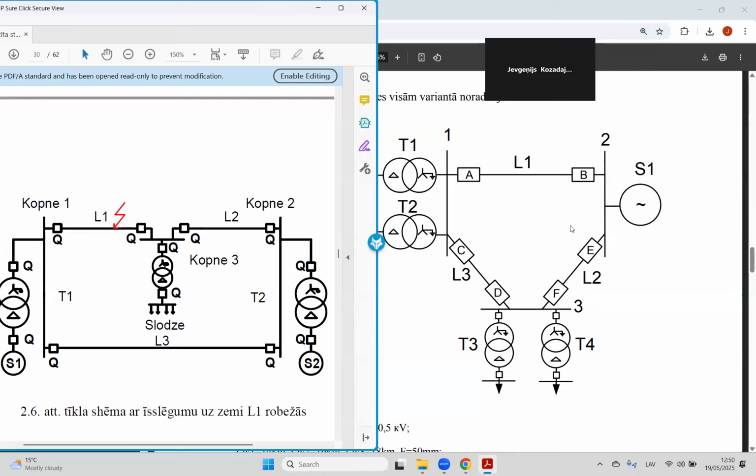But for a transmission network, because it keeps the power system, this is very important. When we keep this loop, we need the possibility to disconnect the fault element from every side, because we have bidirectional power supply. We need a circuit breaker here and here. We have a protection device here, and we also need to use directional protection.